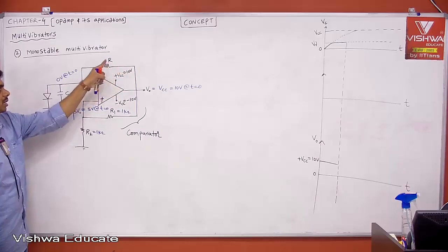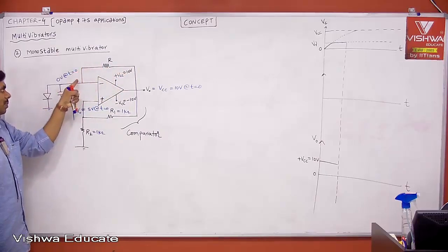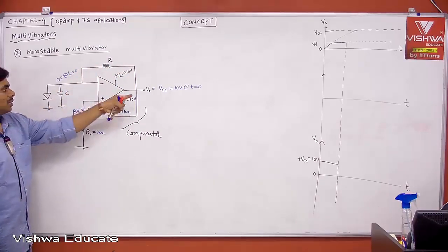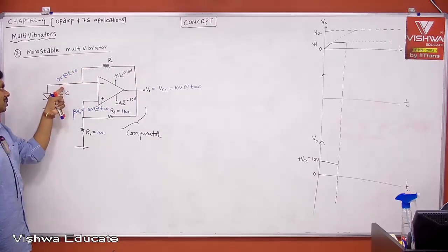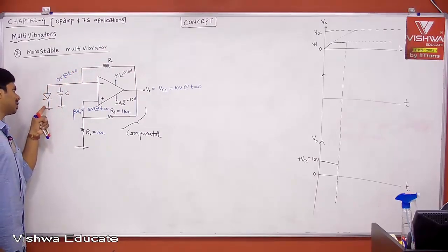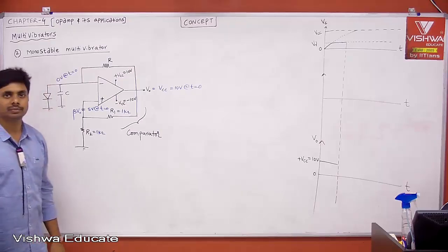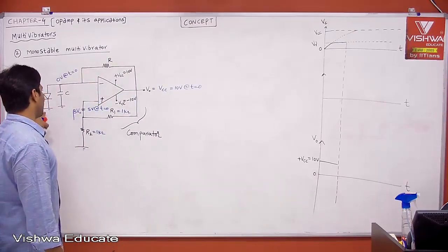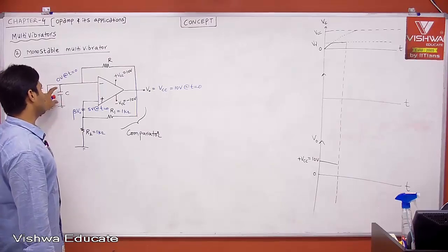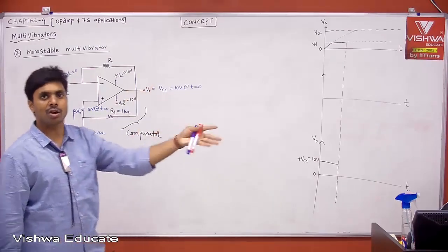whatever current you are getting, earlier if the PN junction diode is not there, your capacitor is charging through R, then whatever current you are getting is the transient or charging current. Now when the PN junction diode is conducting, instead of flowing through the capacitor, it will go through the PN junction diode and then always maintain V gamma. There is no current entering into the capacitor. The capacitor charges to 0.7 and it stays there because current is not entering into it.